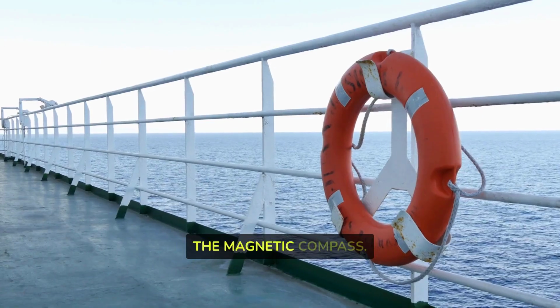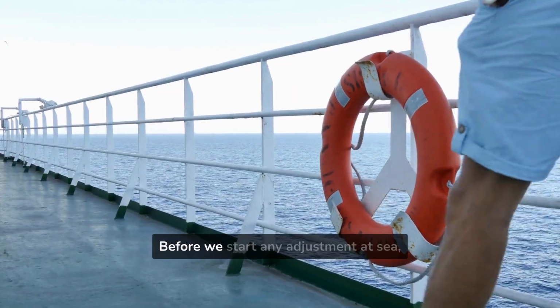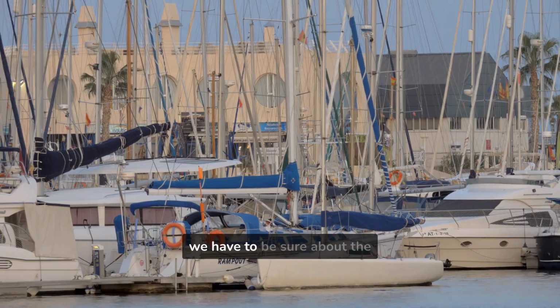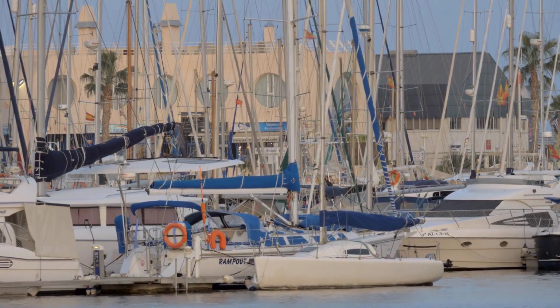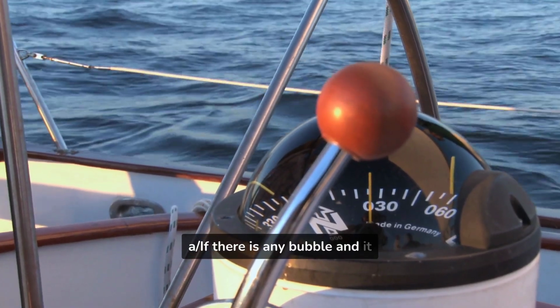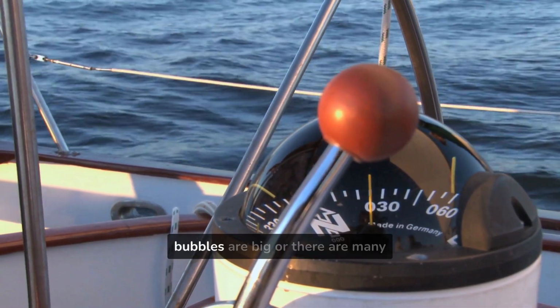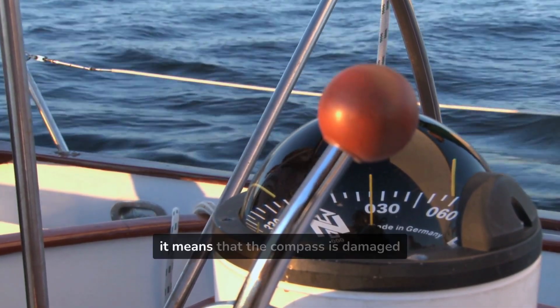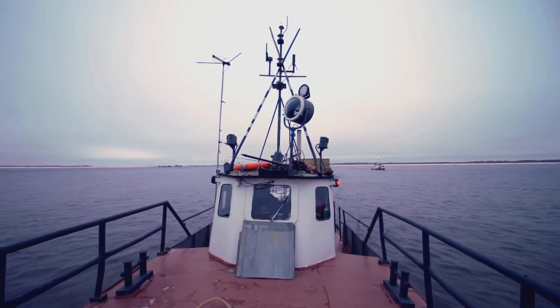Procedure for adjusting the magnetic compass. Berth tests and adjustment. Before we start any adjustment at sea, we have to be sure about the following points, which we have to check when the vessel is alongside. Physical checks on the compass and binnacle: if there is any bubble and it is not very big, we must remove it. If the bubbles are big or there are many of them, it means that the compass is damaged and must be repaired. Remove any slack in gimbal arrangements.